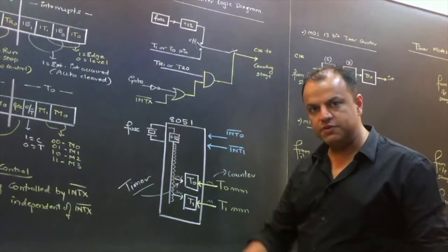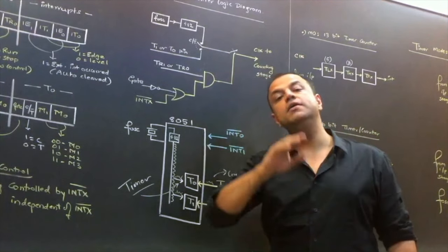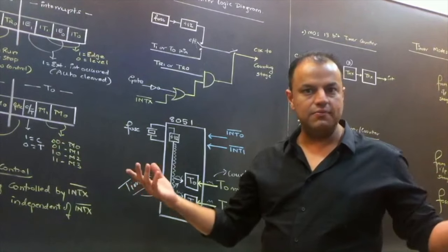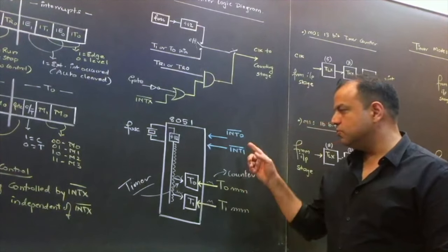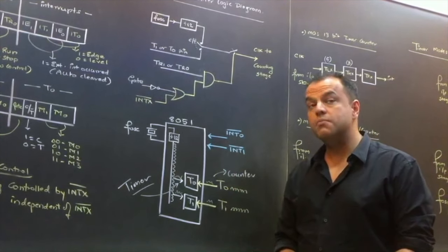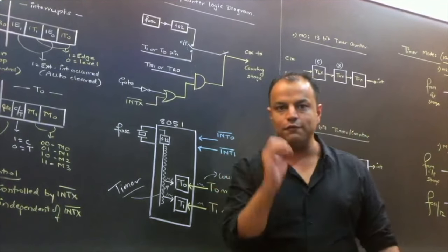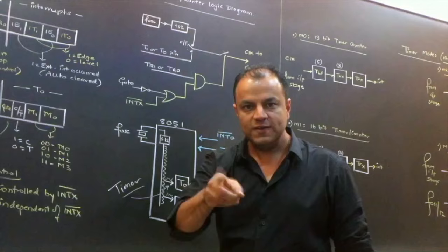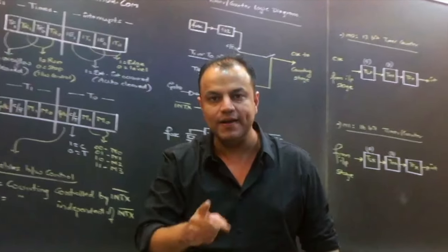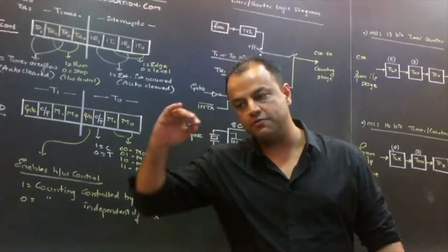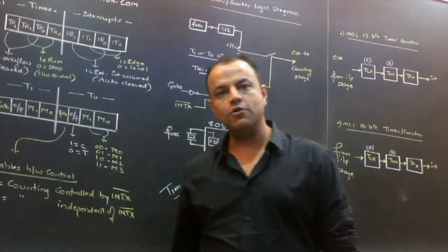When will INT1 be serviced? When the ISR of INT0 is over. Can that take a long time? Yes, God knows how much time it's going to take. So you cannot expect the processor will remember somehow. How will it remember? It's not a human that has a mind. You need a flag to remind the processor, yes, this interrupt had occurred. It is still pending. Please service it. So the flags will remain 1 till the time the interrupt gets serviced. When you go to the ISR, the flag will automatically become 0.